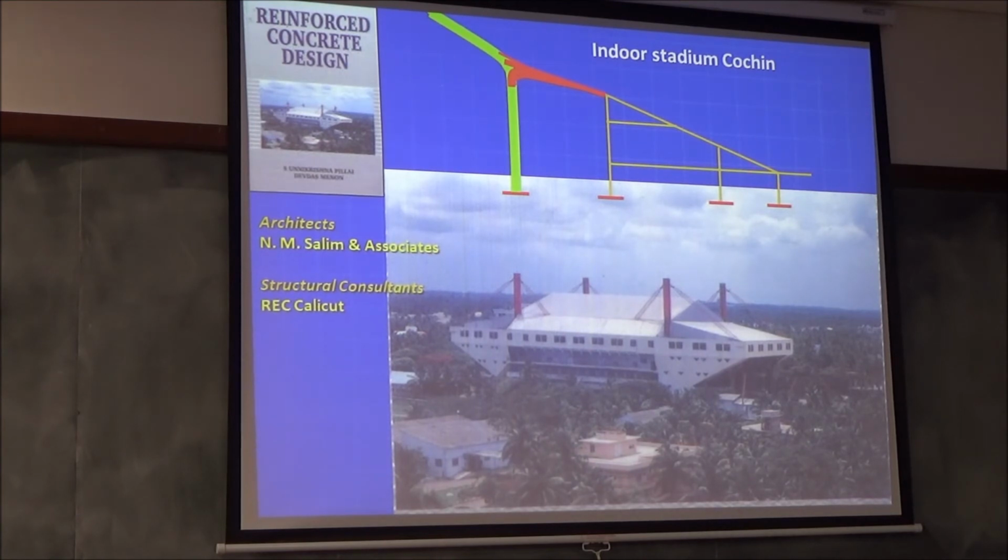We were also involved at the construction time, and I want to tell you many problems if you have time. At construction, we were really concerned because they were going at breakneck speed. There are these cantilevers, for example, this cantilever is here, and they were not ready for putting the shuttering for this, and they went ahead and cast the column. So we said this is risky. Why is it risky? Typically they leave dowels here. This has to be cast integrally.